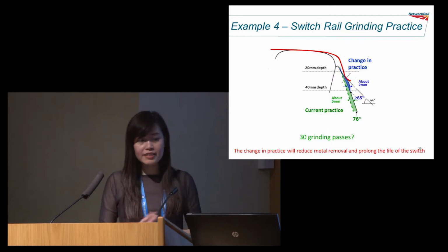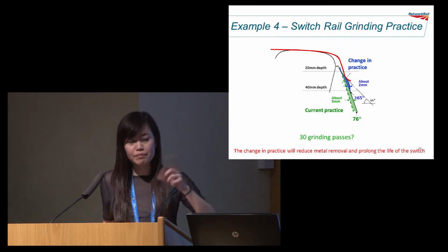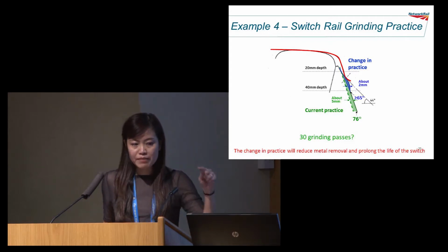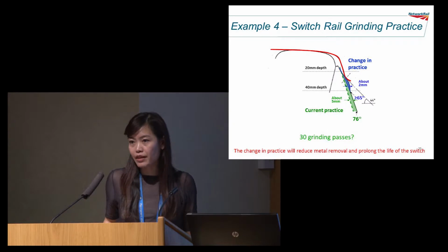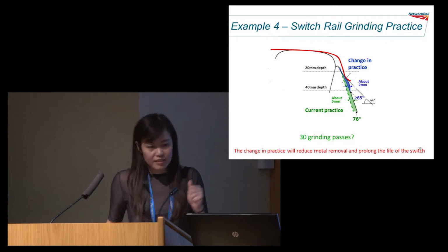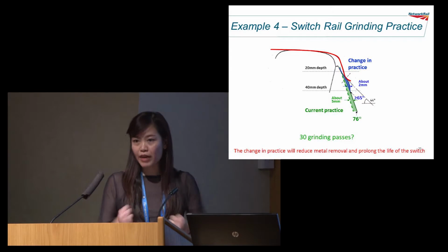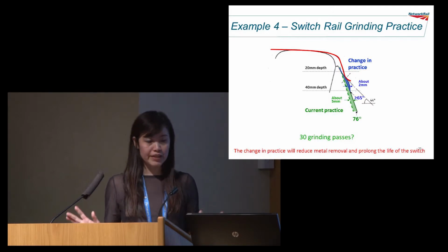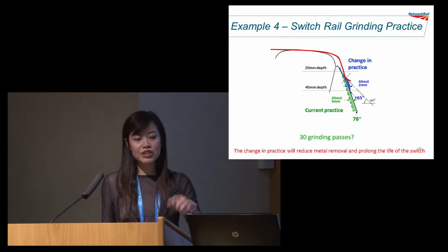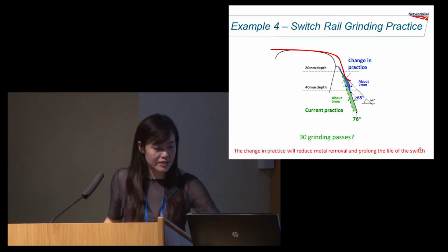I did an analysis and it's all fine. 60 degrees is the limit, and 65 degrees has some factor of safety in it. Also, we only target 20 mil depth down to 40 mil depth, because beyond 40 mil, the wheel will not see it. That will reduce a lot of rush jobs by the grinders trying to get everything done and open to traffic. So there's no more rushing around. Just make sure you blend everything, and make sure there's no discontinuity between the work and what was there before. So that is the requirement.